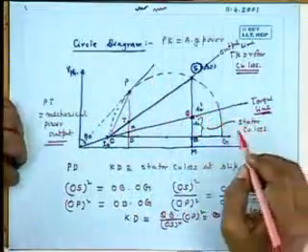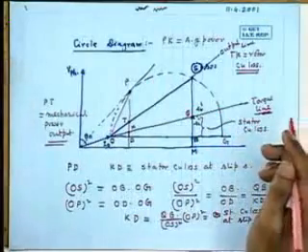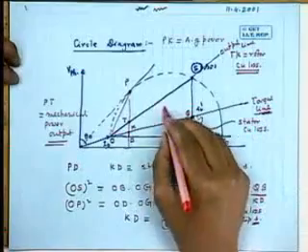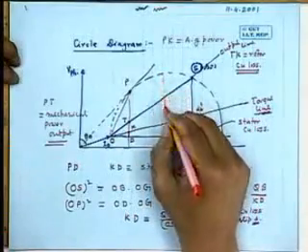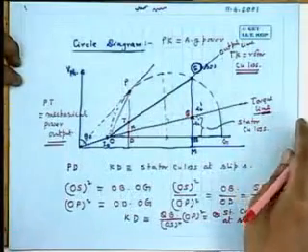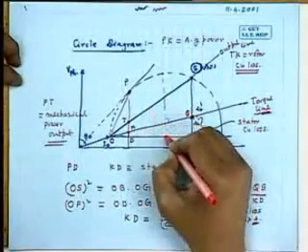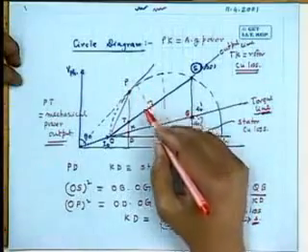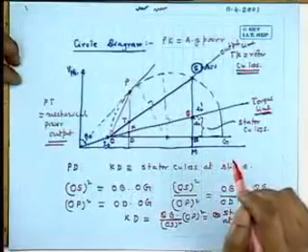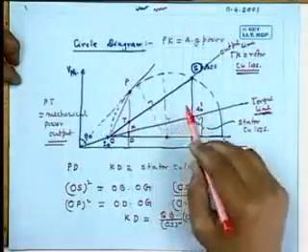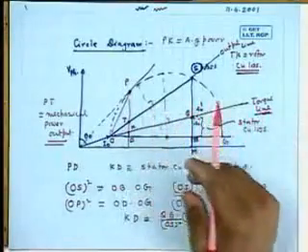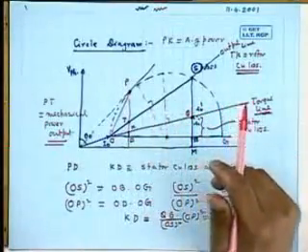And of course the other things remain. If you want to find out the slip at which maximum torque occurs, from the center you drop a line like this, perpendicular, and wherever it meets, that will correspond to the maximum torque. Similarly, for maximum mechanical power output, from this one you drop a perpendicular here, like this, and you get the maximum mechanical power corresponding to that point. Therefore, in the circle diagram, you need not go on calculating everything, just by graphical way you can find it out.